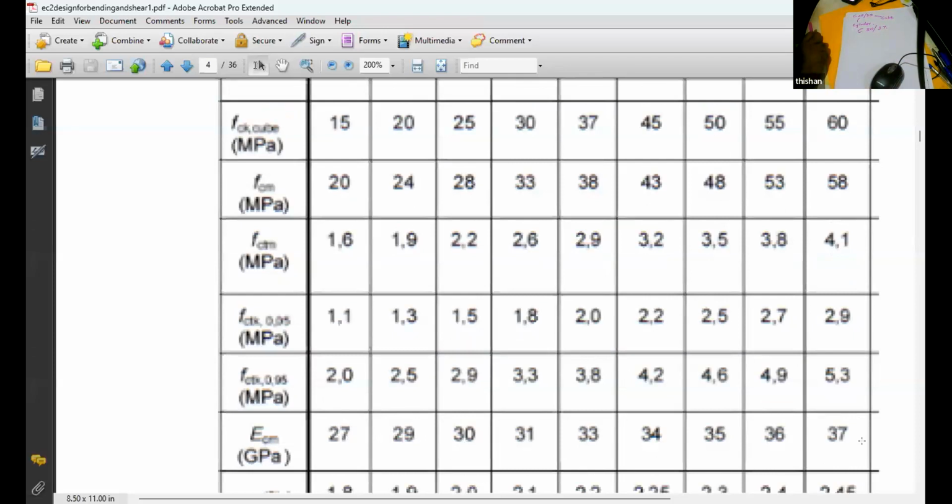So that means nearly a 50% increase in the stiffness of the structure, purely because of the rise in elastic modulus. And that is the key reason for many modern designers to like reinforced concrete for tall buildings, because with the technology we can now go for high strength concrete. So let's see how to go for high strength concrete as well.